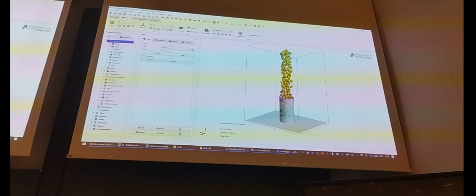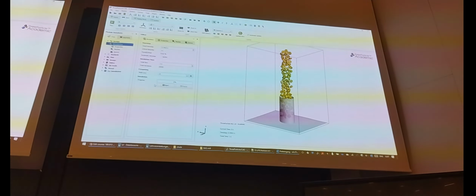That's also a very common mistake a lot of people don't think of. Under Loads, there is no gravity set. On Loads, there is a bar that means gravity, and you need to have gravity in the Z direction, minus Z, minus 9.8 or whatever. Save. And now, let's try it again.